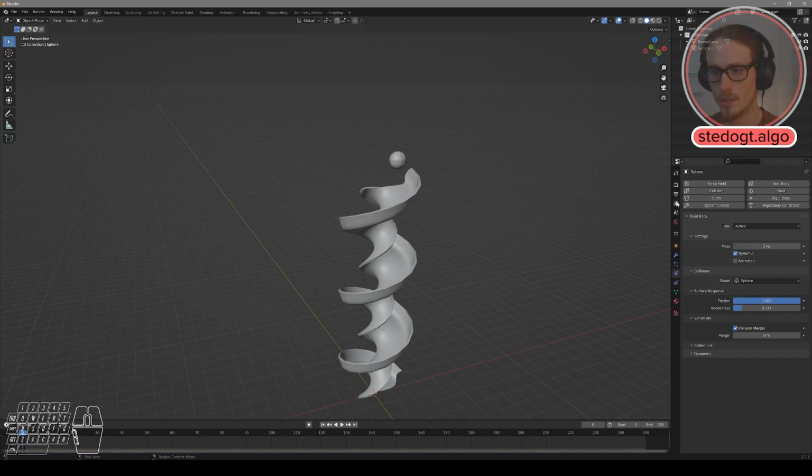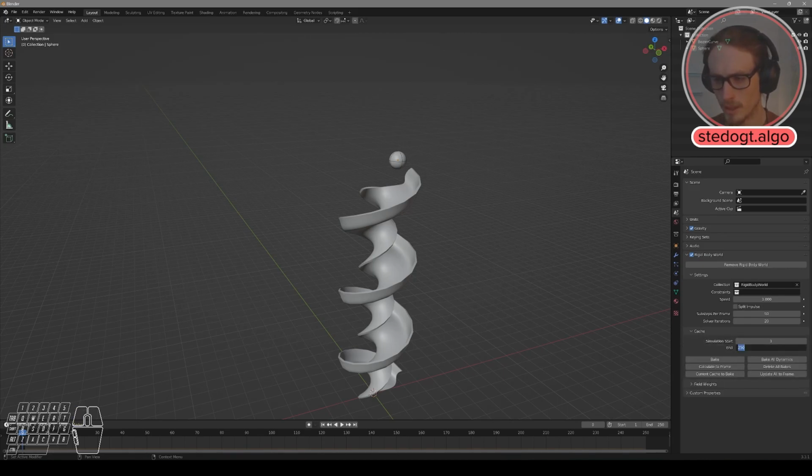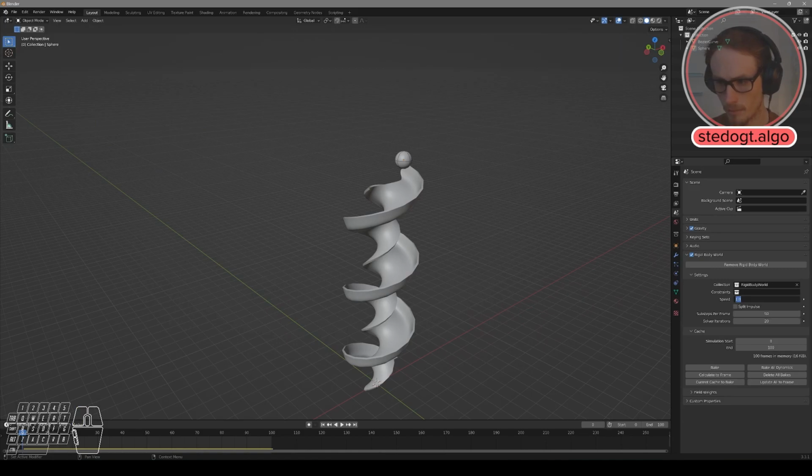Now to begin to simulate our model, we can go to Scene Properties, Rigid Body World. I'm going to increase to 50 and to 20 my substeps and my solver iterations to make that simulation more accurate. And I'll only simulate 0 to 100. I'm also going to change here on my animation timeline 0 to 100. I might bump my speed up to 1.5 and select bake.